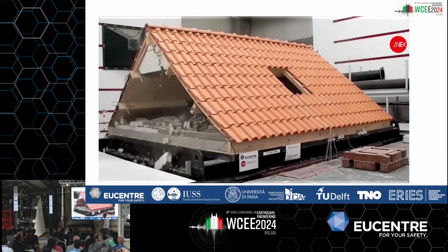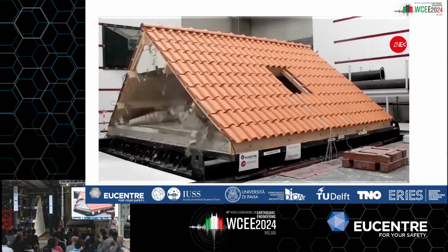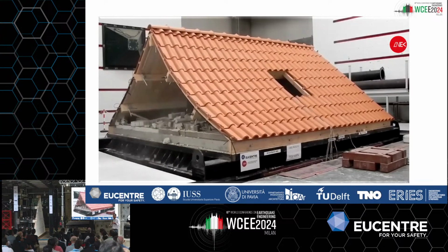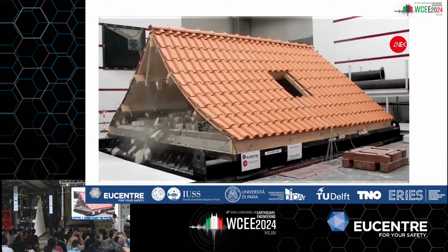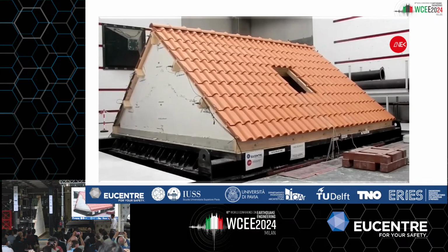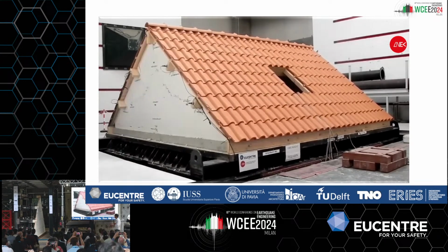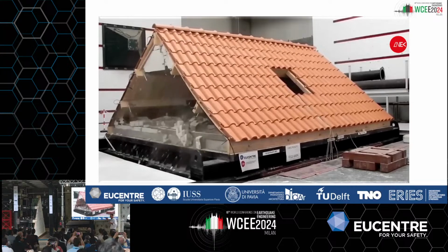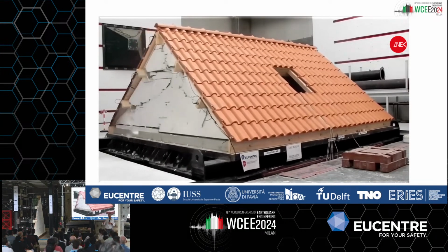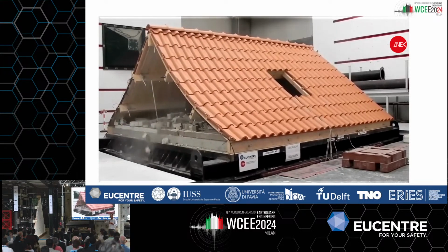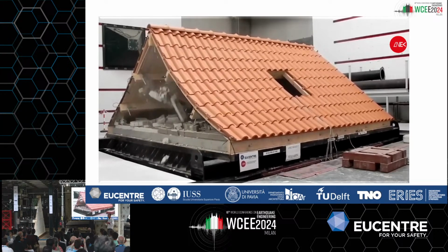Despite this fact, in literature, there is substantially no study on the behavior of these structural elements. The only study that addressed exactly this phenomenon was a study conducted by us, in which we performed this type of test at LNEC, in Lisbon. In that shake table test, we simulated the entire roof, but we had no control of the actual acceleration that we were applying at the ridge level. So we applied the floor motion at the base, and then the flexibility of the roof was doing the rest.